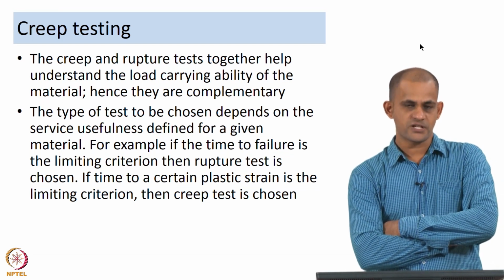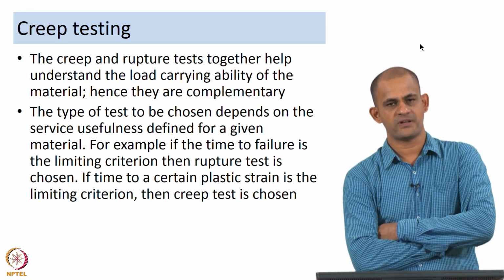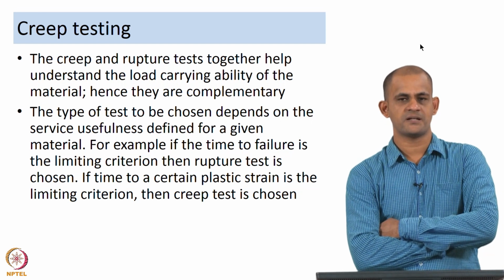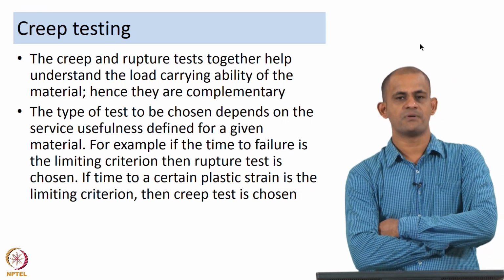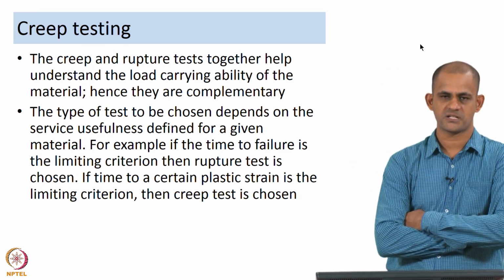And the type of test that you are going to choose depends on the service usefulness defined for a given material. For example, if the time to failure is the limiting criterion, then a rupture test is chosen. However, if time to a certain plastic strain is the limiting criterion, then a creep test is chosen.